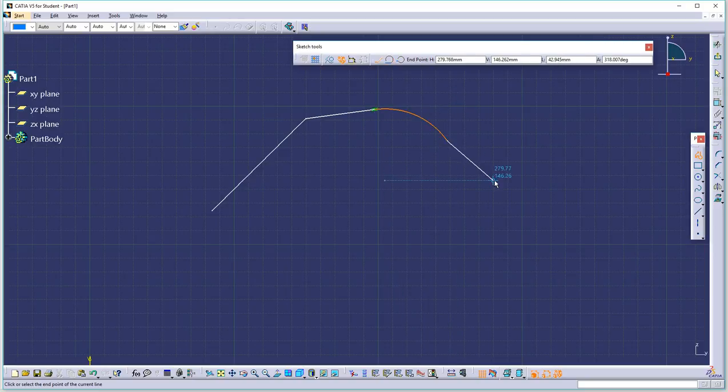Tap, and then if I press and drag away for a sloppy tap, it throws me into arc mode. Now notice the arc mode is tangent arc mode. If I pick this arc mode, now I'm in an arc mode that allows me to create arcs that aren't necessarily tangent. Okay, and double tap.